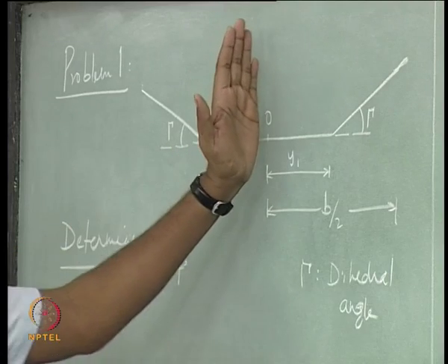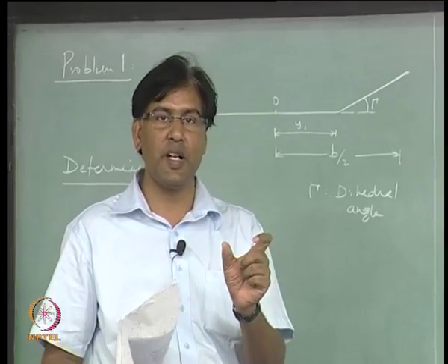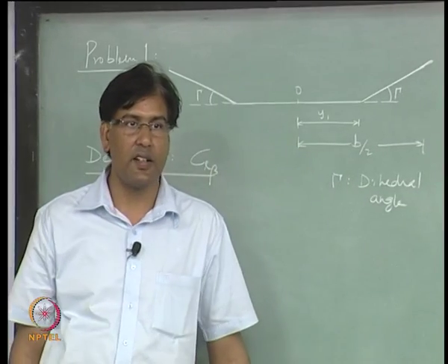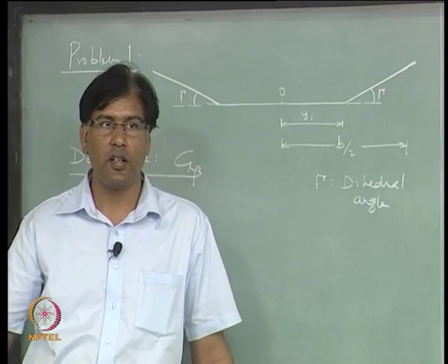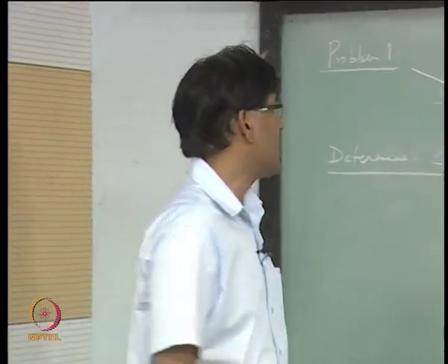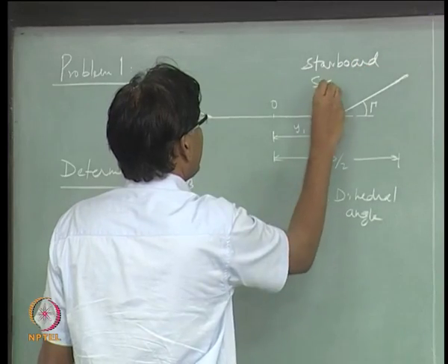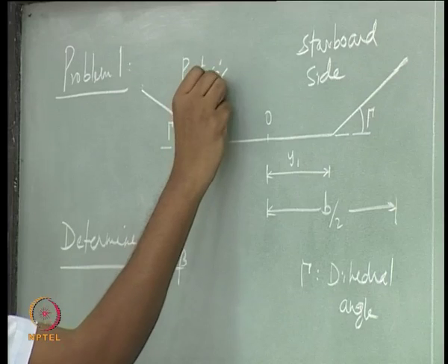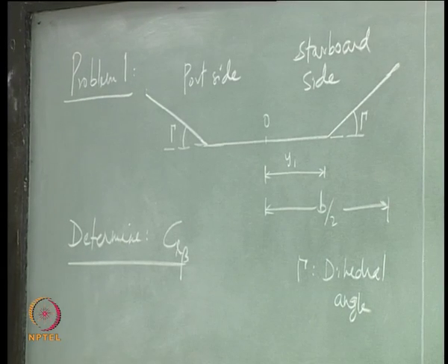Okay, about this. How do you go about solving this? I want to find out CL beta. So I will assume that there is a beta, positive beta coming from this side, right? What is this side called? The right side of the wing? Starboard, right? The right wing into the wind is the starboard. And this is the port side. So positive beta is right wing going into the wind, right? So I want to find out this parameter CL beta.